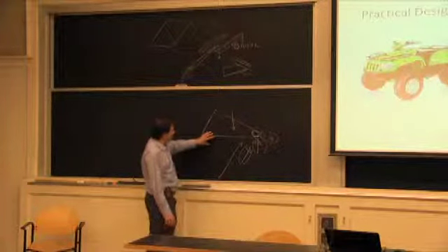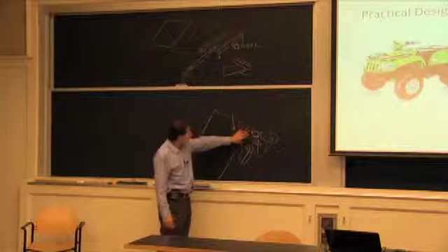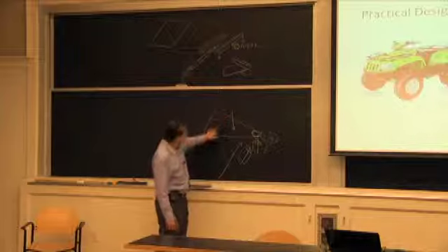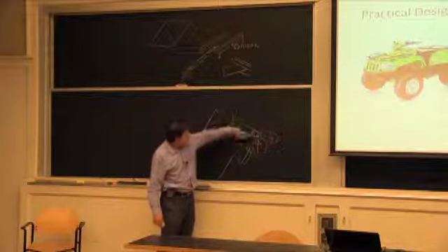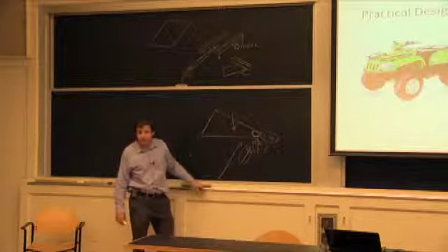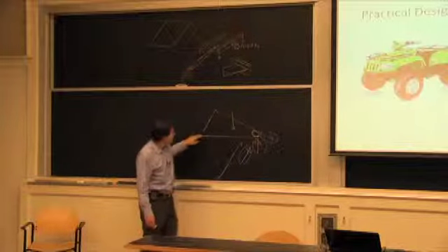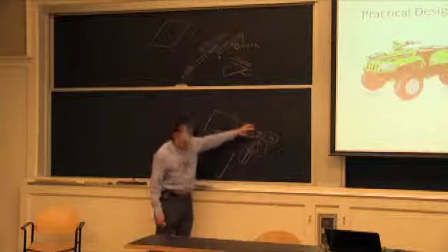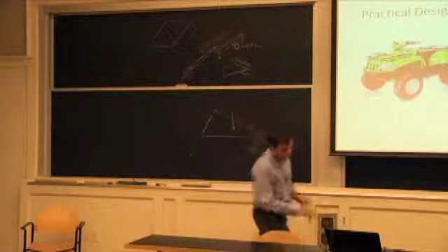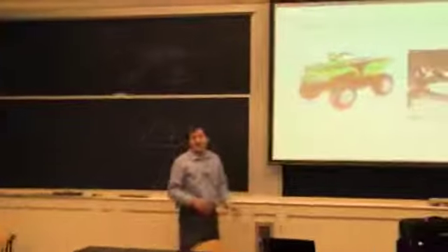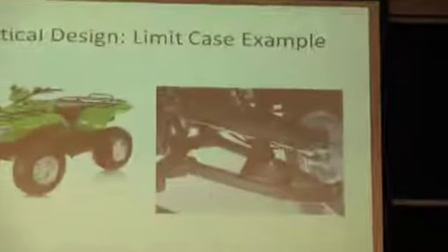In other words, you can tell that there's been a lot of years of experience knowing you want to spread these members instead of having just one piece coming out, to take into account the back and forth force from applying the brakes. That's why it's spread into an A-frame as opposed to just a piece sticking out. Now, for the upper arm, and you can see it on this graph, the spreading between the two members is less. So it becomes tighter here